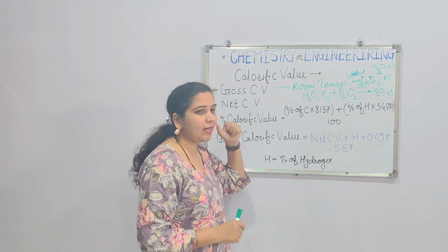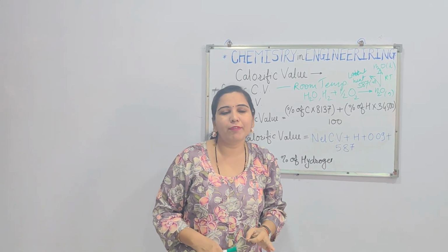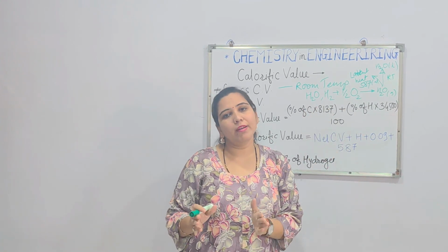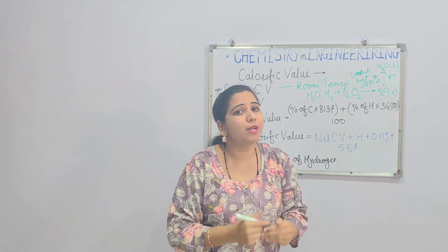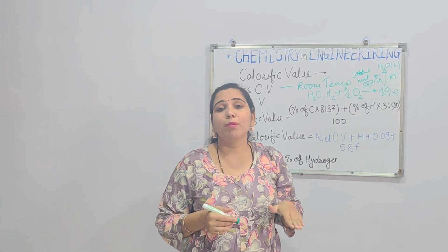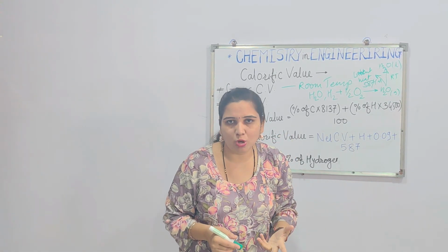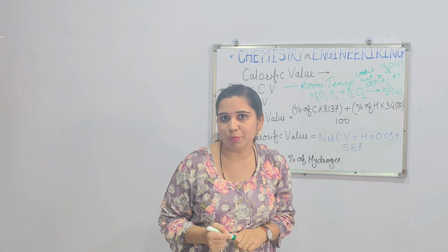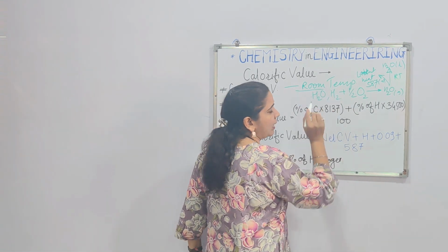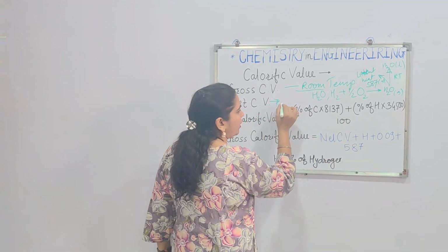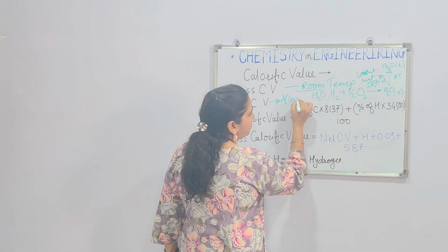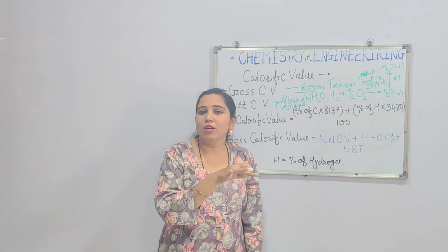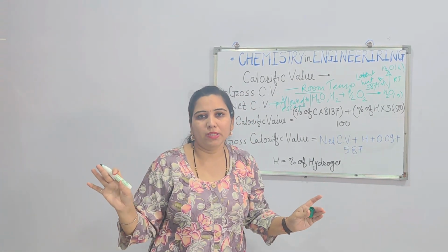Now, what should be the net calorific value? Net means a lesser or lower calorific value. It is again the same calorific value, but the products produced at the burning temperature of the fuel are allowed to escape into the atmosphere. Here, instead of cooling to room temperature, the products are allowed to escape. It means that at that temperature the reaction has just been opened.